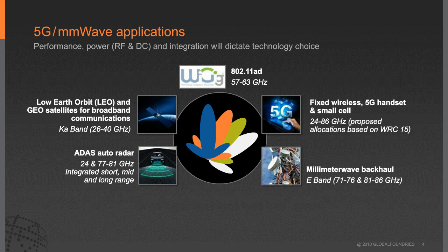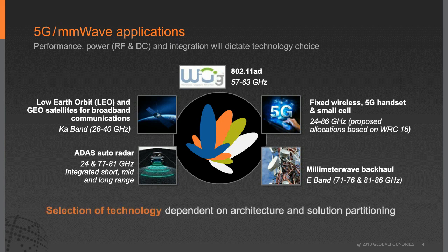This happens because of concentrating all the energy in one direction instead of broadcasting in a big beam with a wide angle. Since the transmit power requirement is reduced, the requirement for each power amplifier connected to each phased array element is reduced. This allows silicon-based technologies to be used for phased array antennas instead of the III-V semiconductors like gallium nitride, gallium arsenide, which are typically used for high output power amplifiers.